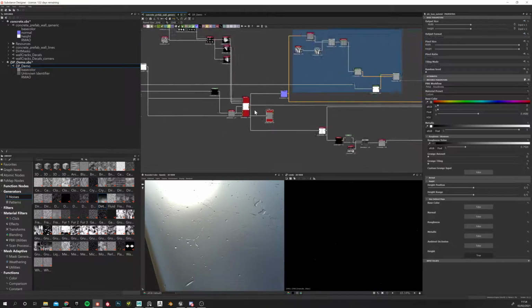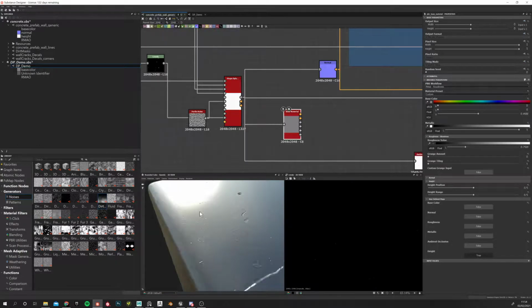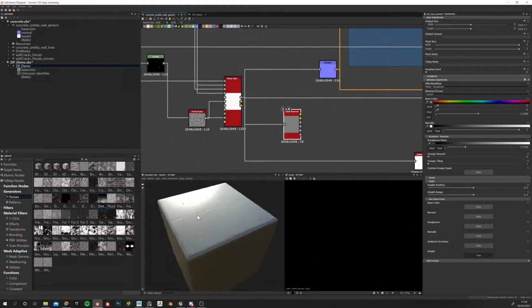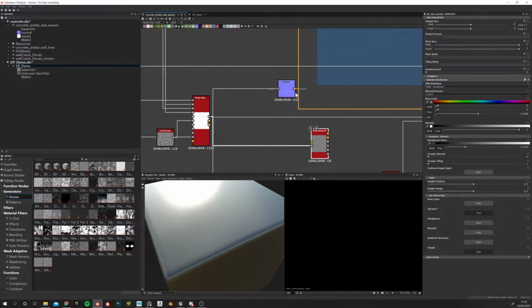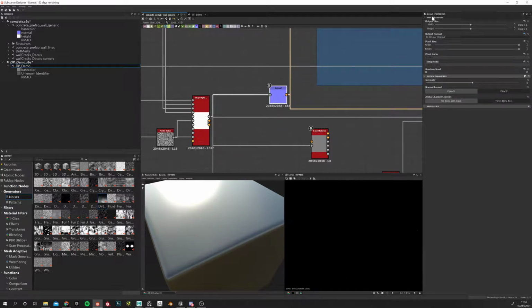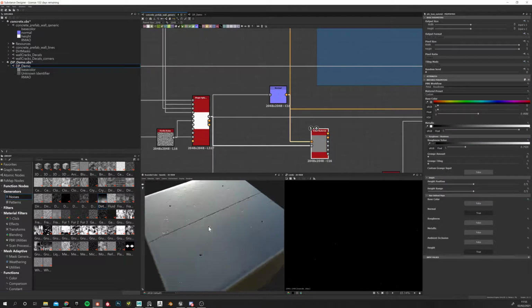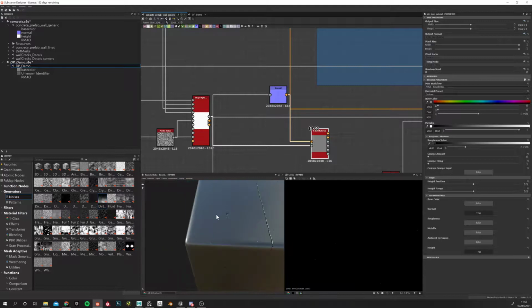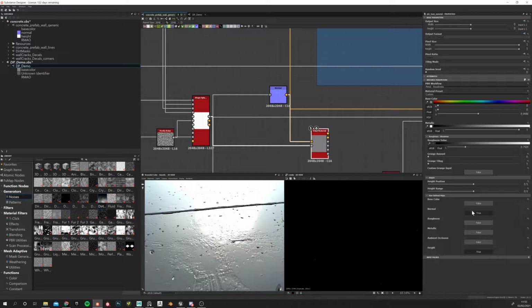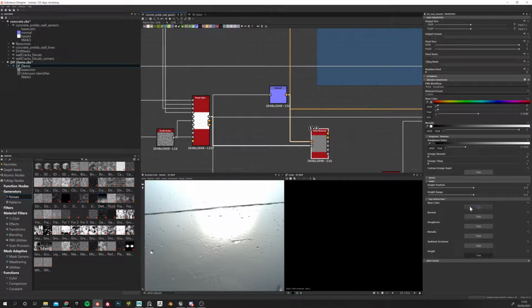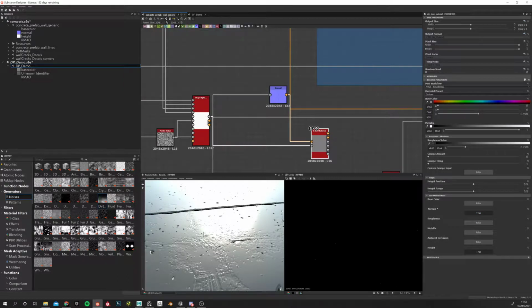So now that you have the height map, which is this one here, look, this is the height map. Then from there you start deriving your normal. You can see that normal here. If you want to see the normal here, then you have to take the original material, enable the normal, and now I can take, it's just a map now called normal. You connect to there. You can see now, that's a normal. Now it starts looking a bit more realistic because it has the normal map. See? Before, if you disable the normal map, look, it's flat, but with the normal map, it looks more detailed.